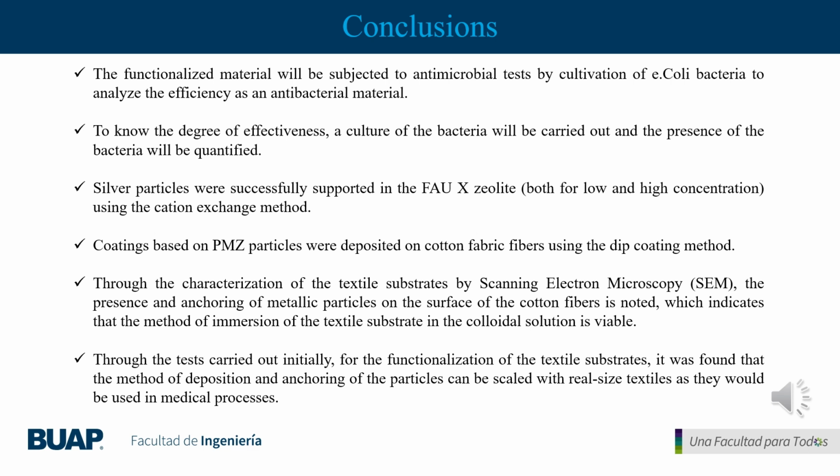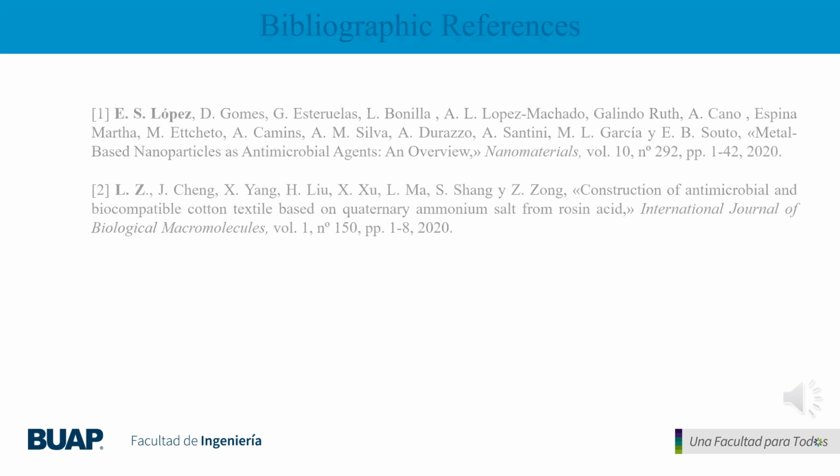Likewise, through the characterization of the textile substrates by scanning electron microscopy (SEM), the presence and anchoring of the metallic particles is denoted, indicating that the method of immersion of the textile substrate in the colloidal solution is viable. Likewise, through the tests carried out initially for the functionalization of the textile substrates, it was found that the method of deposition and anchoring of the particles can be scaled with textiles in real sizes as used in medical processes.